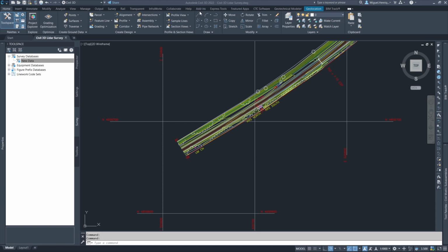So you just use your line, you make this grid just with a distance of 100 meters. This is really important. Why? Because we can use this to be able to create this file that we will use to import the coordinate system to Revit. So let's see how we do it.